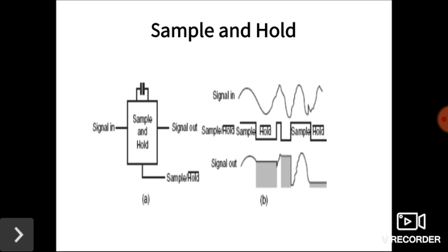The sample and hold unit is unable to hold the input voltage for a long time. The captured value of the voltage decreases slowly. However, most ADCs are fast enough to convert the analog voltage sampled within a reasonable time duration, so that the distortion may be neglected for practical purposes.